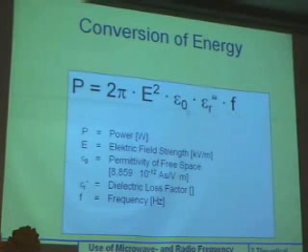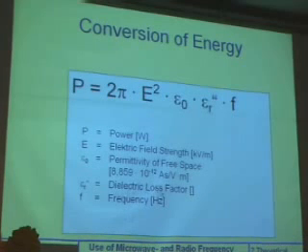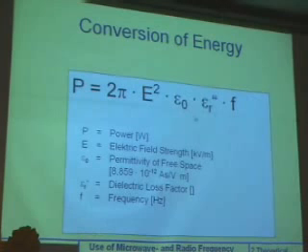These factors come from the product, and one of the most important factors is epsilon R. Epsilon R is what we call the dielectric loss factor. You may perhaps wonder why we say this is a loss factor, because it is very important for us. The higher it is, the more heat we get, but this is the interpretation of an agricultural engineer, as I am. Those people who found out this basics are broadcasting engineers, and they are not interested in losing electromagnetic fields and power. They want to keep it working, because then they could broadcast over a wider range of areas. In their case, this is really a loss, but in our case, it is exactly what we want.